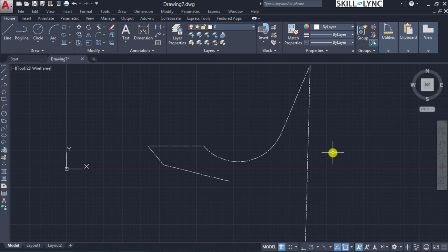So what this reverse does is, if the line type is a text-based line type, it can change the text orientation, or if the line type has a different line width, then also it can change the orientation, as it is reversing the vertex order. Let us look into them one by one.